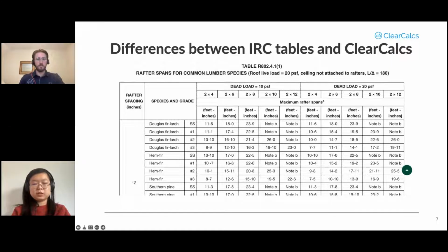And in particular with the roof pitch, we apply gravity loads over the inclined length instead of the plan length. So live and snow loads are generally overestimated. And then to correct for this, you can multiply your loads by the cosine of the incline of the pitch.